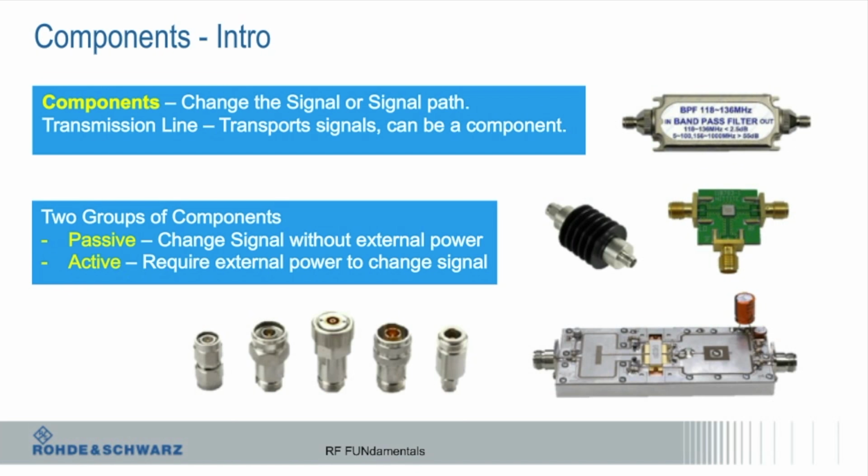You can see here the center pin. Often on a less expensive connector, that's the pin, and that's the thing the pin goes into, and you'll see often this is white. That's a Teflon dielectric. The dielectric material between the conductor and the outer ground shield may be a dielectric material. The better connectors, metrology grade connectors, are always air dielectric. They're much more precise, they're defined over a wider frequency range, and have much better performance.